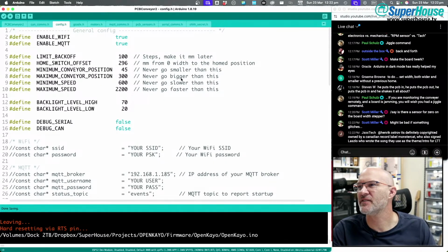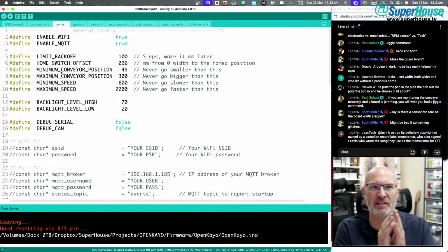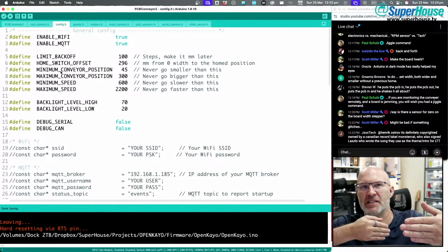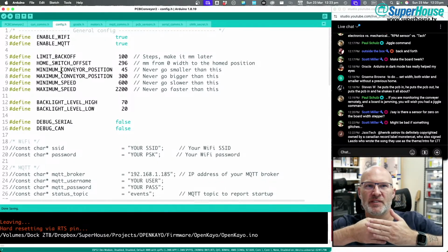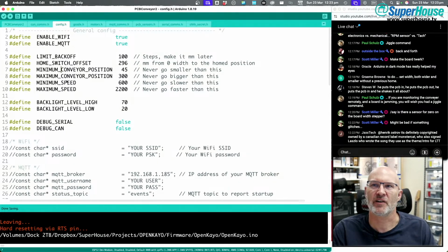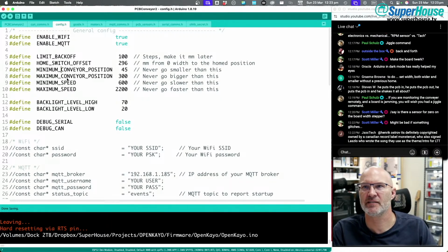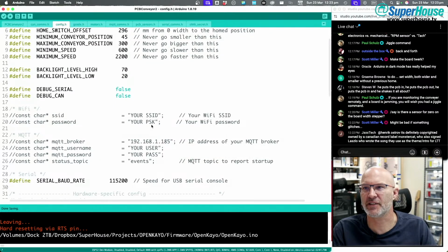Is there a sensor for 0 on the board width stepper? Yeah, so I know what you mean. At the moment what it's working on is a sensor for the maximum open position, but there is no sensor for the minimum closed position. I could potentially add another sensor for that so that it zeros by moving in instead of zeros by moving out. But yeah, we'll see if it's necessary. I have a feeling it won't.